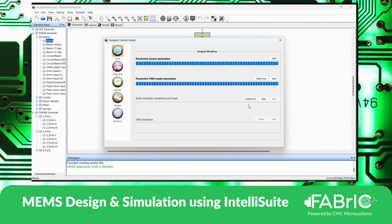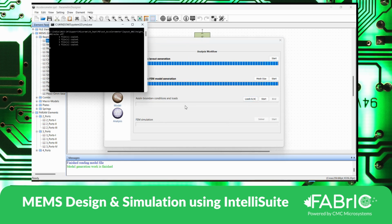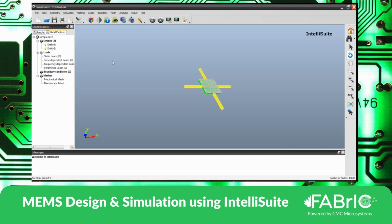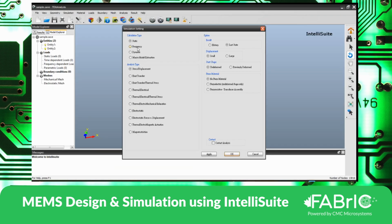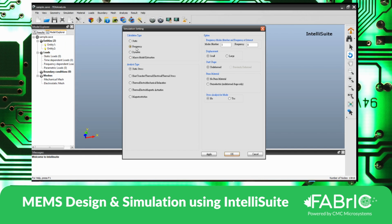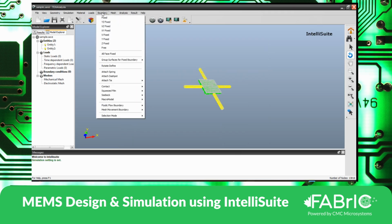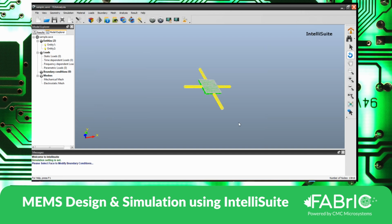Okay, so now I want to apply boundary conditions and loads. When I click, this geometry opens up, the base model opens up in the thermoelectromechanical module. There I set my simulation. I would want to do frequency-based simulation, then apply OK. I want to fix the boundaries.